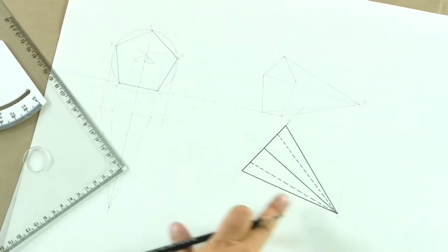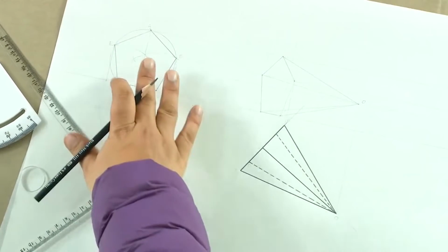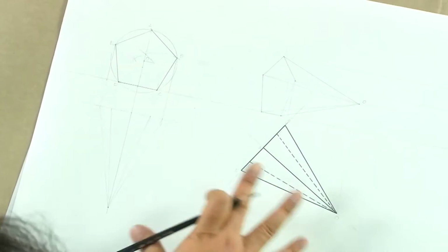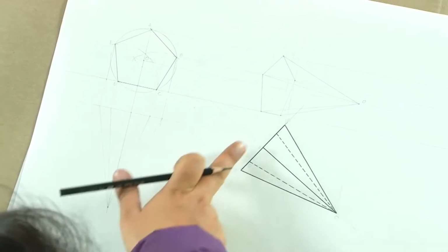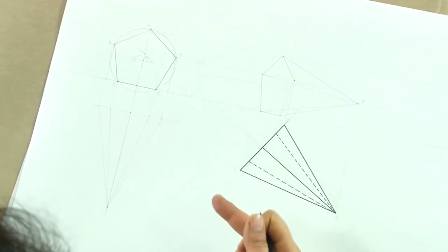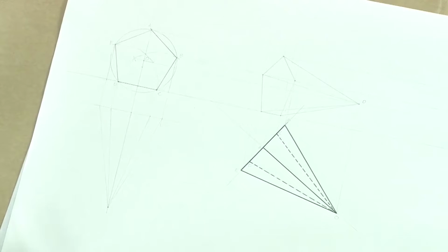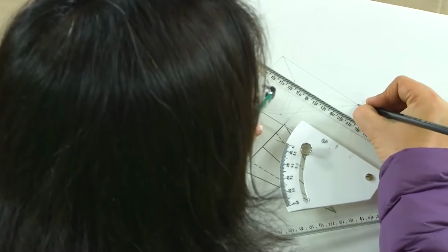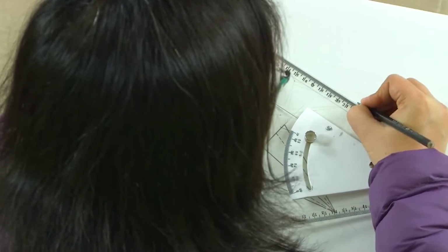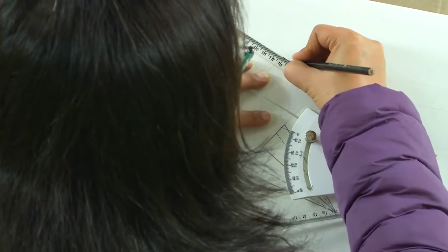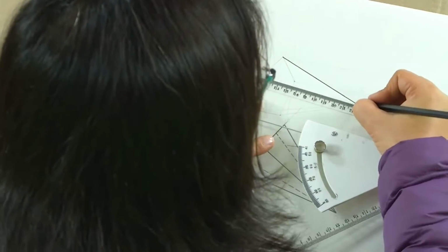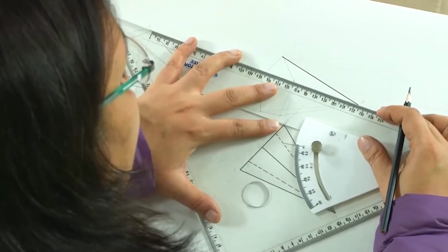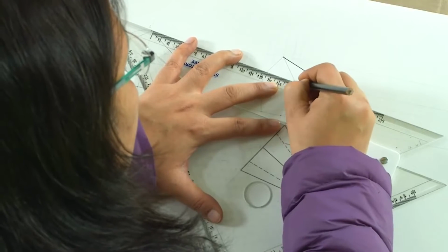So, this is the top view of the cone, and now we will start to draw the front view. Now, this cone is inclined like this, so the base is not visible, only the outline of the base will be visible, which is what we have to keep in our minds. And let us draw. So, only the edges which are visible will be made solid, and this line, which is OB, is actually a hidden line which goes behind the cone itself. So, we draw a hidden line here.